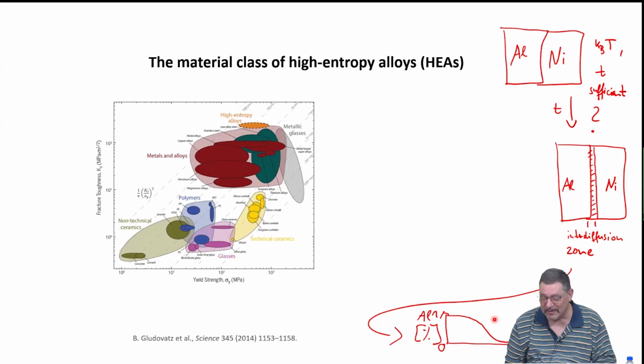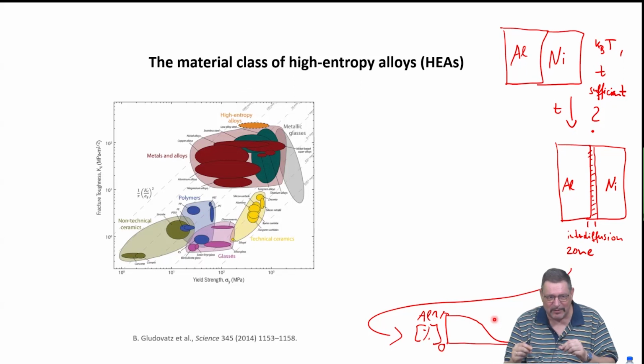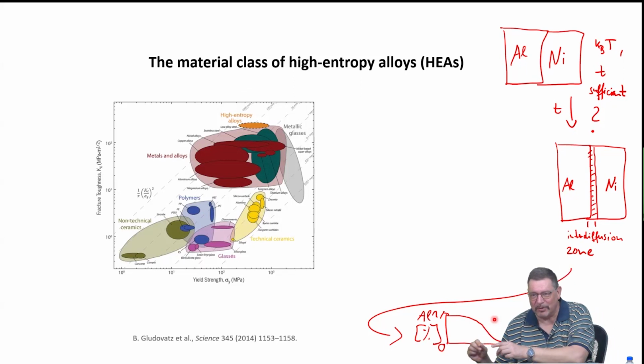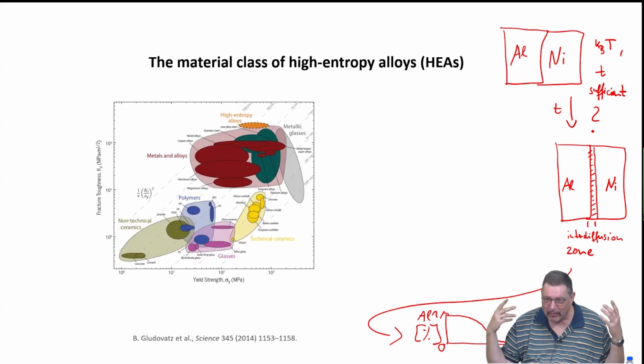And so this is very important to keep in mind for later on, that diffusion, my old teacher told me, diffusion can be easily confusion because there are so many diffusivities, right? So you have to really be very precise, because self-diffusion, interdiffusion, tracer diffusion, impurity diffusion, it all means something different, and it has different boundary conditions connected to the term.